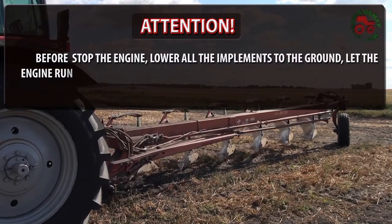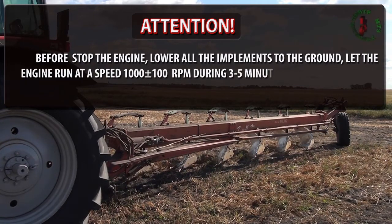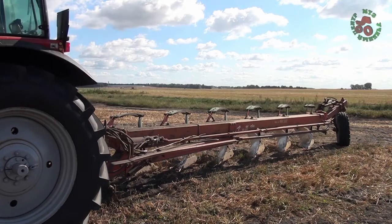Let the engine run at a speed of 1000 plus or minus 100 rotations per minute for 3-5 minutes. It will help to reduce the engine coolant temperature. To stop the engine, do the following.